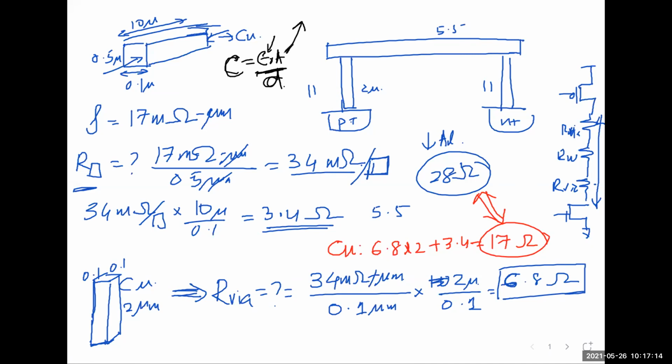That's why in analog you don't want to spend a lot of area. Area is cost in any IC design. The more the area, the more the cost. It's just proportional. If your chip area goes from 1 millimeter square to 2 millimeter square, the cost of that silicon die is going to double. And nobody wants that. So in analog, that's why they want high K dielectric.